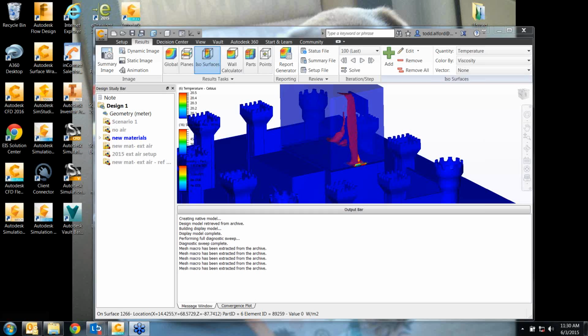Yeah, I think it's pretty straightforward. I mean, the real basics are remove the solar dome, assign solar walls and solar windows with correct solar heat gain coefficients and U values, and then either apply a film coefficient or use the ambient reference within the solar heating dialog. That's pretty much it. It seems to work really well. I'm fairly pleased with being able to see some of that, because it's definitely a huge difference when it comes to human comfort.